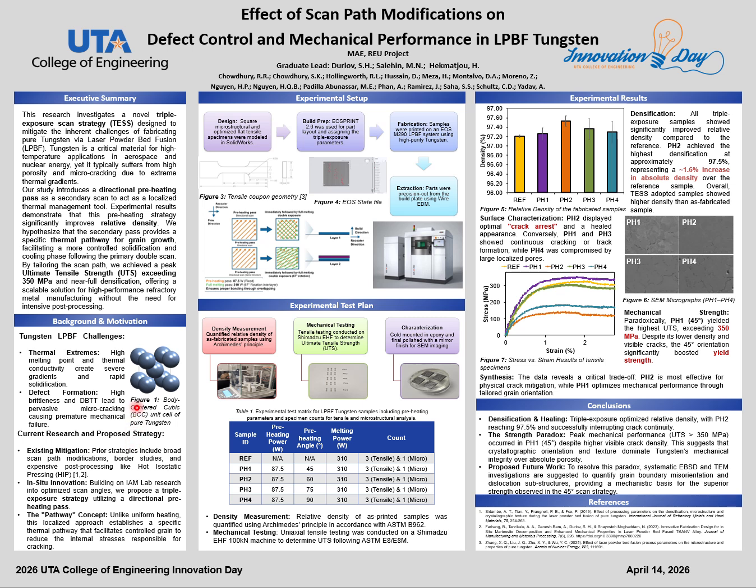So there have been lots of studies ongoing, like scan path modifications, border studies, or other expensive post-processing. But we don't want to focus on that. We want to focus on an in situ technique, which can be used during the fabrication to improve the properties of the part itself. So we want to propose a triple exposure scan strategy, or TESS, as a directional preheating pass. What we expect is it will create a thermal pathway that will heal the cracks and pores as the sample is building up.